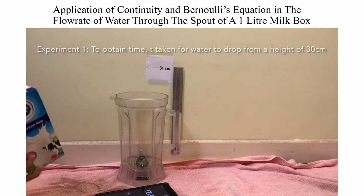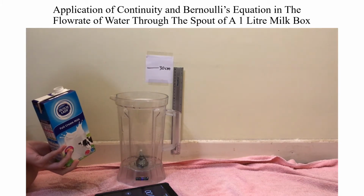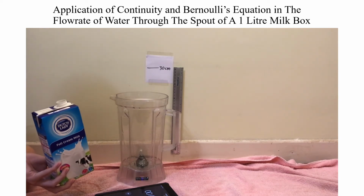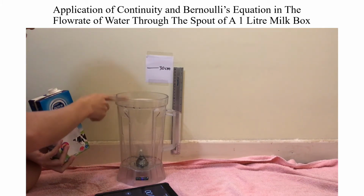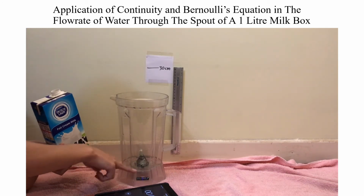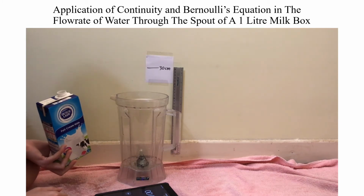Okay, this experiment is conducted to find the value of velocity at point 2, which is V2. So in order for us to find V2, we must actually find the time taken for the water to travel at the distance of 30 centimeters until the bottom of this accumulation tank. So with that time taken, we can take 30 centimeters and divide by the time taken, and we can find the velocity at point 2, which is V2.